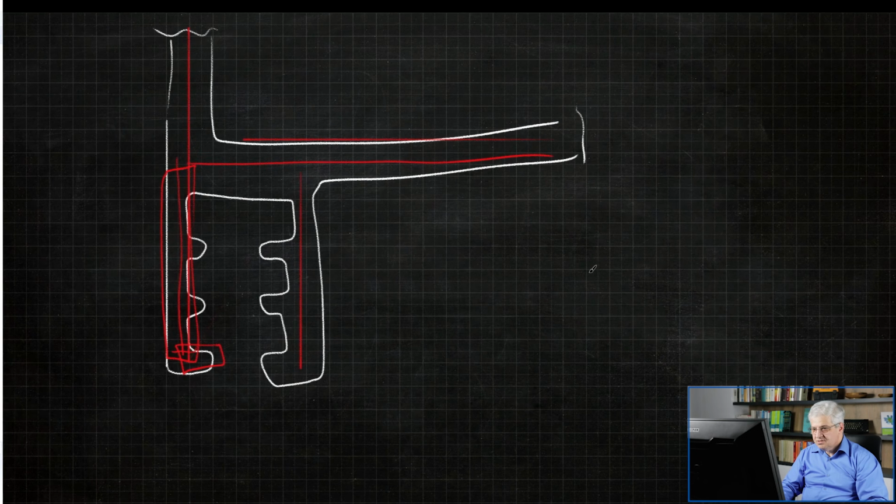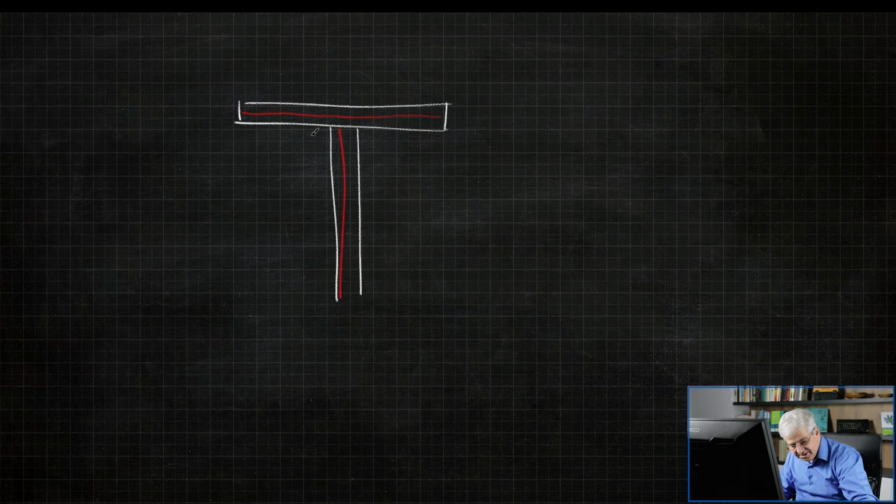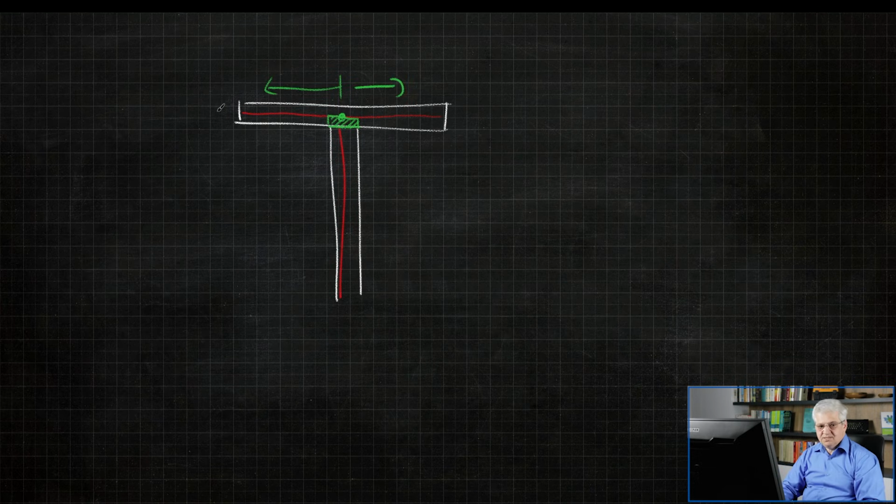So let's deactivate it. If you use these thin-walled cross-sections, then draw it. This is the center line with the thickness, and draw another center line directly to the boundary, not to the center. Then it's correct. SCIA Engineer adds automatically here a small part of the cross-section, connects it, and splits also this one line to 2 lines. You can check it, but it's done automatically. It's also described in the online help.